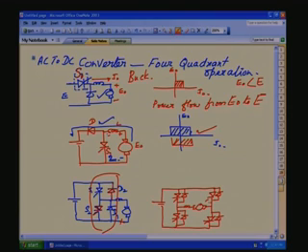That means as far as the load is concerned, both voltage and current can be positive as well as negative. Okay? So, this can be used. This configuration is called the four quadrant chopper. This is also a single phase inverter configuration. Now the load we want both positive and negative, so the load will have alternating current and voltage. Positive and negative means PWM operation is possible.